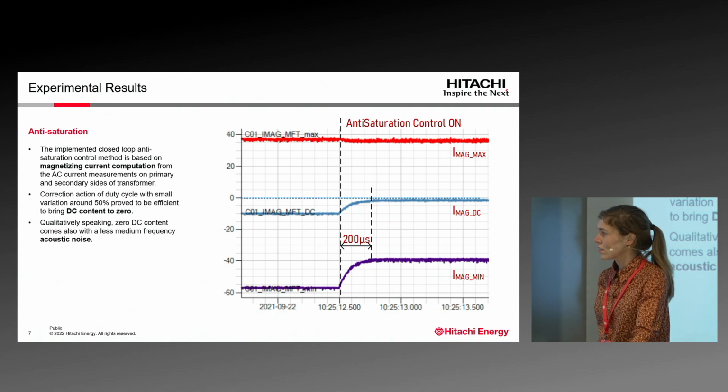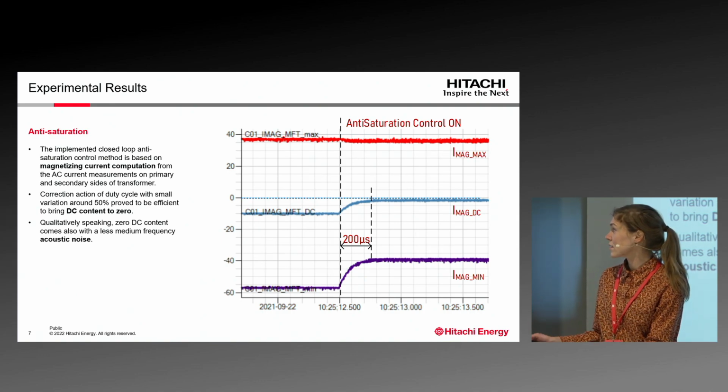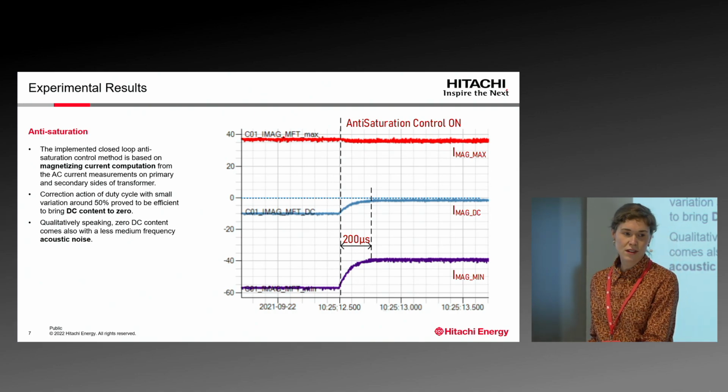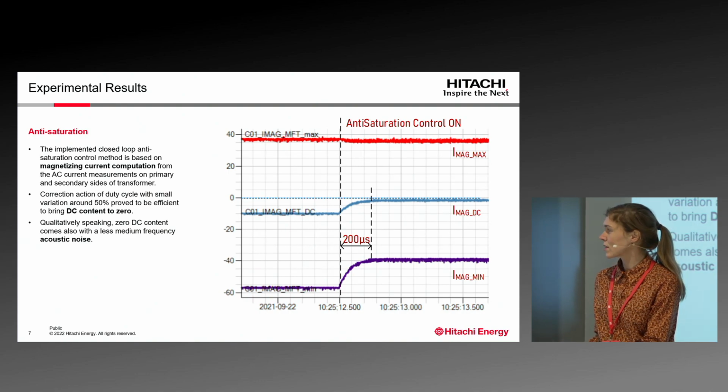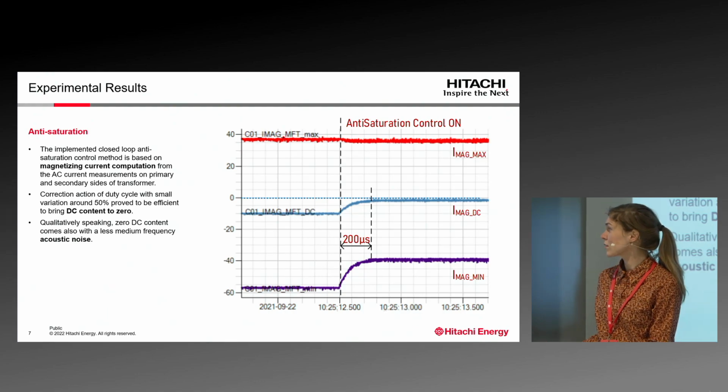An interesting observation from the lab was that, after turning on the control, the acoustic noise in our lab was drastically reduced. So if you have some magnetizing current, the core vibrations, you can hear them acoustically. So that was maybe worth mentioning.